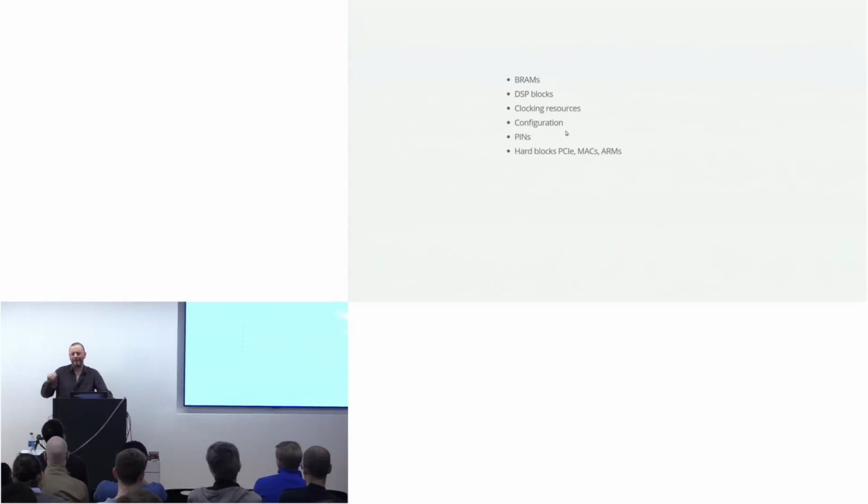And they also do some magic, I'm not sure quite how this works, where they can align the clock across the entirety of the silicon, because there are propagation delays there and they matter. So when you clock logic, you have to do it in a specific way in an FPGA using these clocking resources. There's a whole big manual about configuration of them.